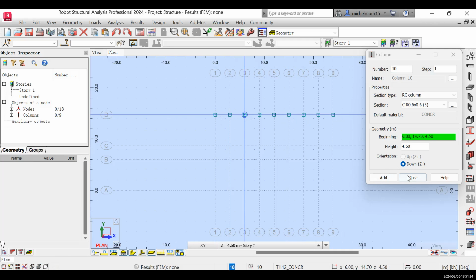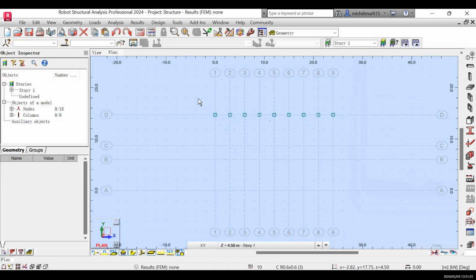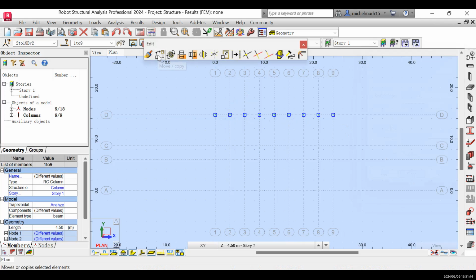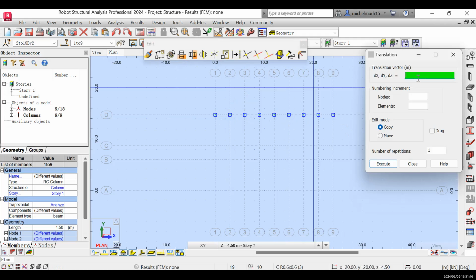Okay, and then come back here, copy everything, all right, and come here, edit, and then move and copy. So I'm gonna copy it in the Y direction. X direction is 0, no copy. 0 means no copy. And in the Y direction, I'm gonna copy it in L1. L1 equals 6, but it's going down, so it's -6, right? And Z direction is 0, right?